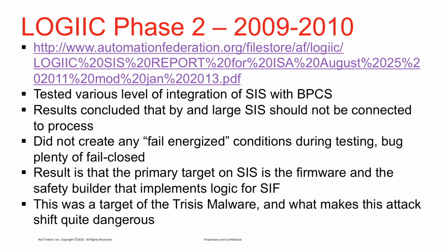So in other words, from a cybersecurity standpoint in safety instrumented systems, the 2 main avenues of approach are going after the safety builder or going after the firmware of the device, both of which were actually implemented in Triconex. Okay? So to some level were implemented in Triconex. So that's one of the reasons we really don't want you integrating these components. Now, I know there's some vendors that are doing it. We can have that discussion offline. I'm not calling anybody out. There's different ways to do it. Okay?